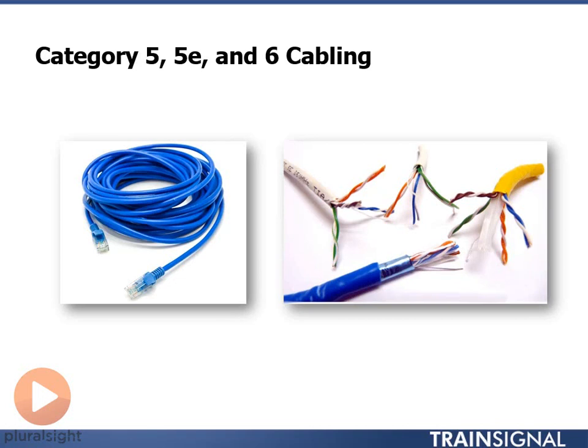Why is this problematic? Well, here in a Cat5 cable, we have 8 wires, and we use 4 of them for transmitting data. Well, if we ran those wires straight, and we put them all right next to each other, and we sent data across them, what would end up happening is our data would consistently jump from one wire to the other wire and cause this issue called crosstalk. And crosstalk is a huge problem because when crosstalk happens, this is where we're going to start dropping bits from our Ethernet frame and have to do lots of retransmits. Exactly what we do not want.